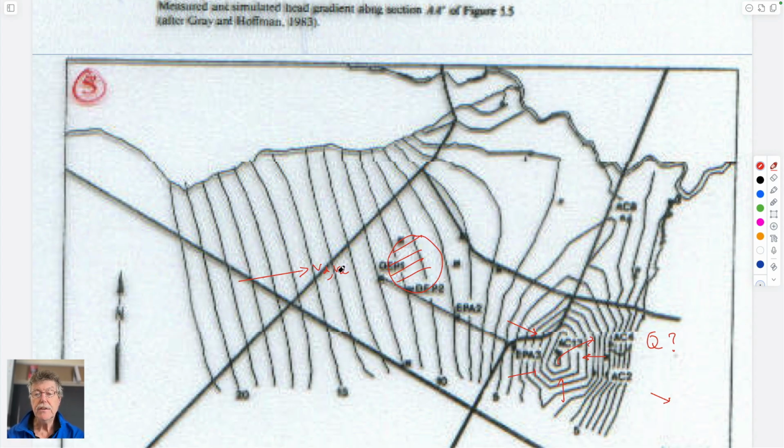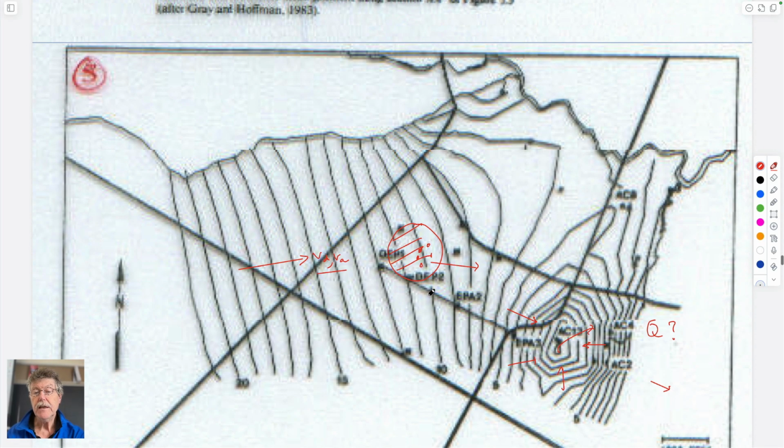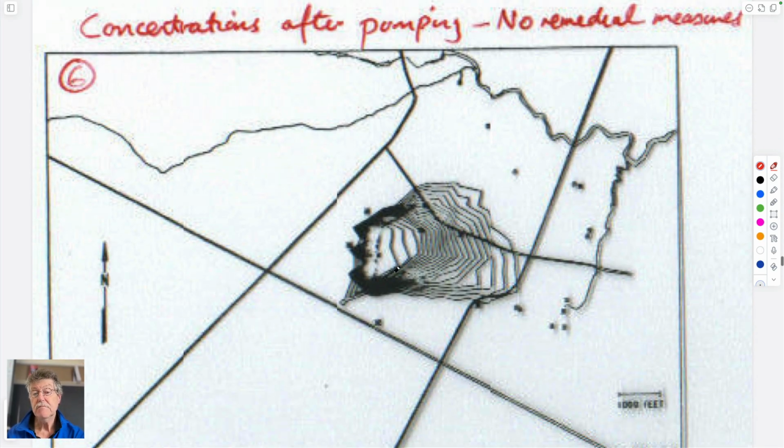But now, if you know what these are, you could also add these as advective fluxes. So you could think about, in the simplest way, releasing particles of contaminant and see where it gets carried downstream in a given time. And those are the simplest explanations of this kind of process that we can look at. So if you have the flow field, then that allows you to define the velocities. So you could release lots of particles at this site virtually in a computer code, and they'd get carried downstream, and you could contour their concentrations to be able to say what the plume would look like.